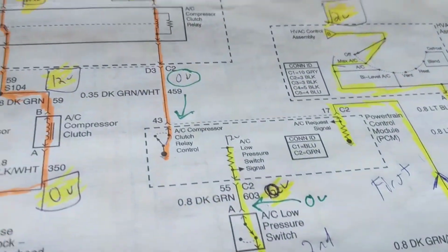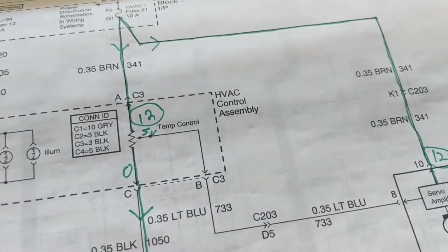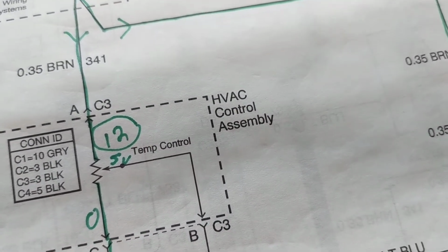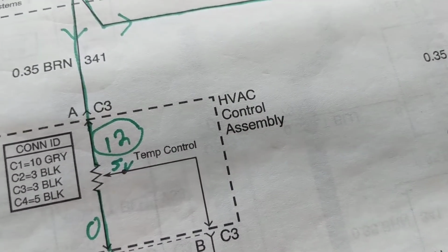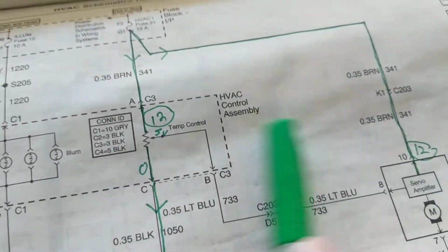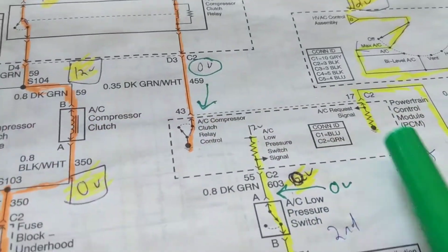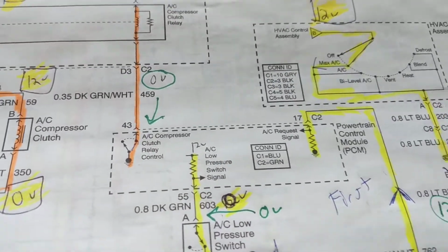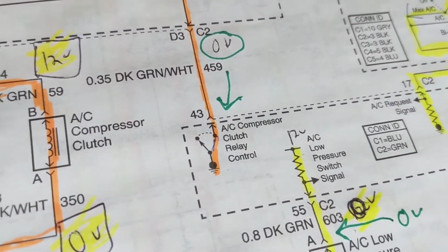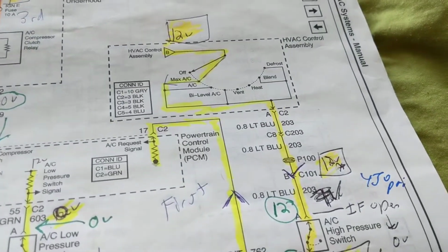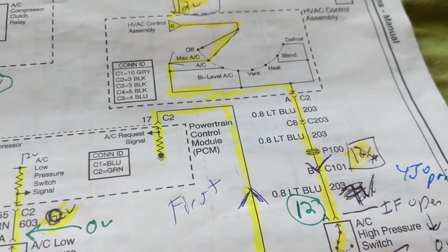The cold air, where it comes from the air conditioner, obviously. The heat or the cold comes from this, the temperature actuator, right? You're either going to have it from the heater core, or you're going to have it from the evaporator, or you're going to have it going to the vents. That's the airflow is this. The cold air has to come from here. Obviously, the heat has to come from the coolant and the heater hoses and the heater core. So that's the first thing that I do. So let's say I put it in defrost. I don't have even cold air in that.